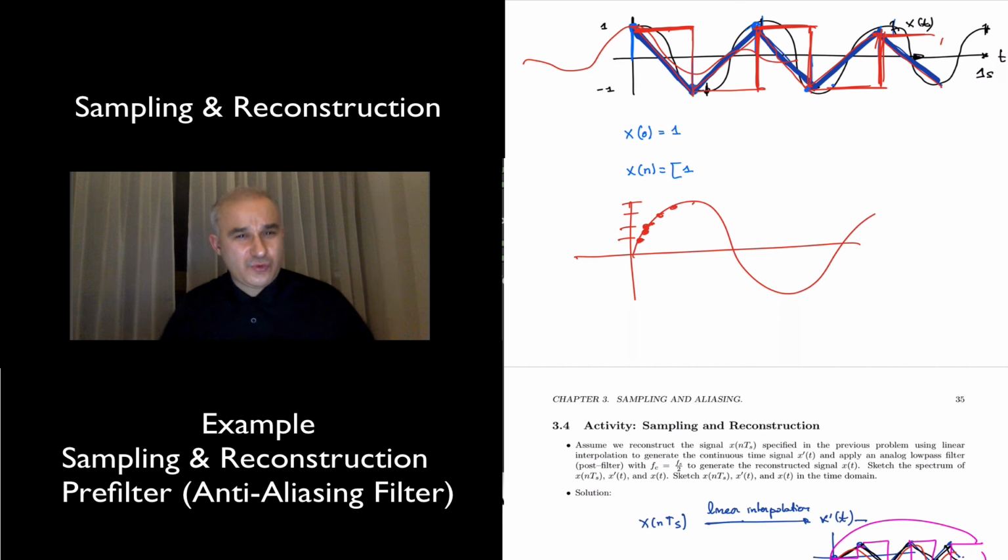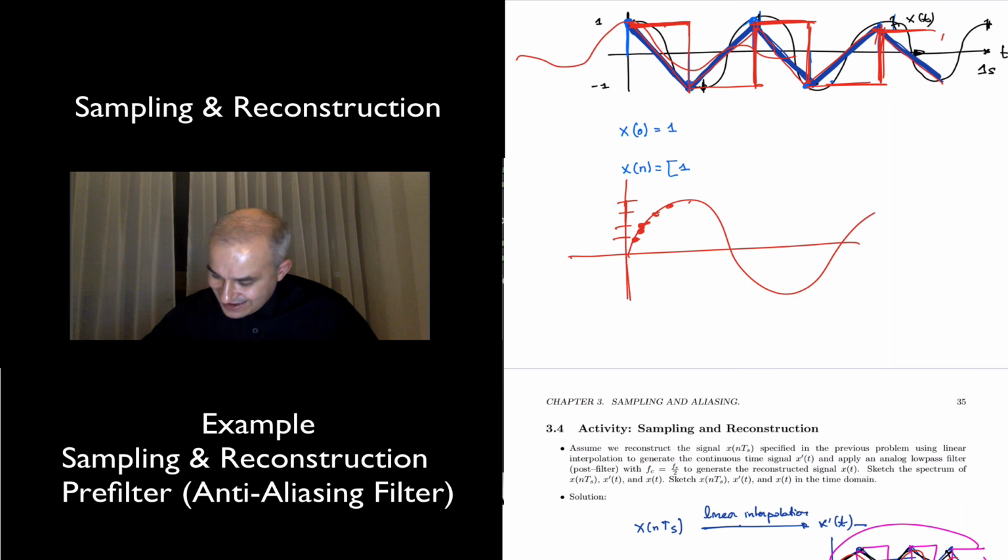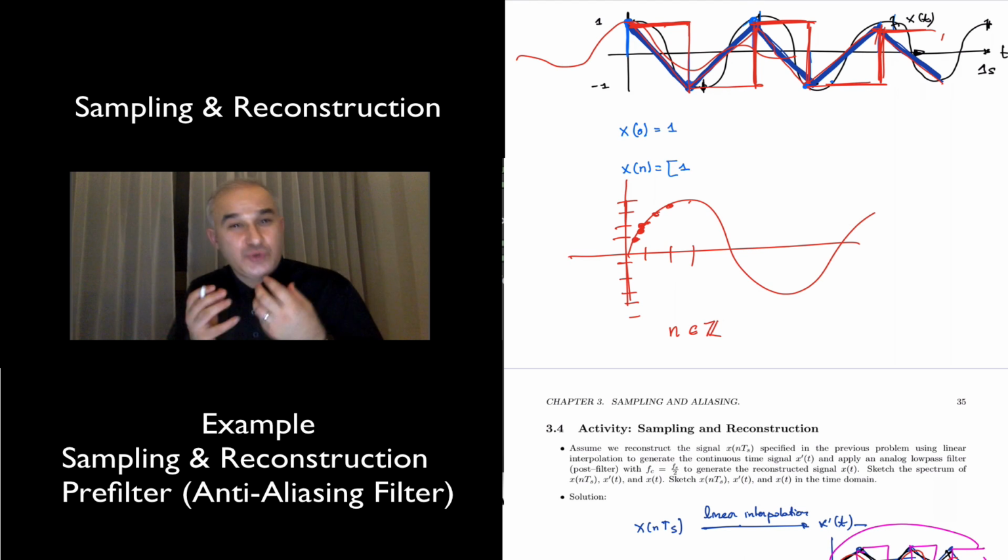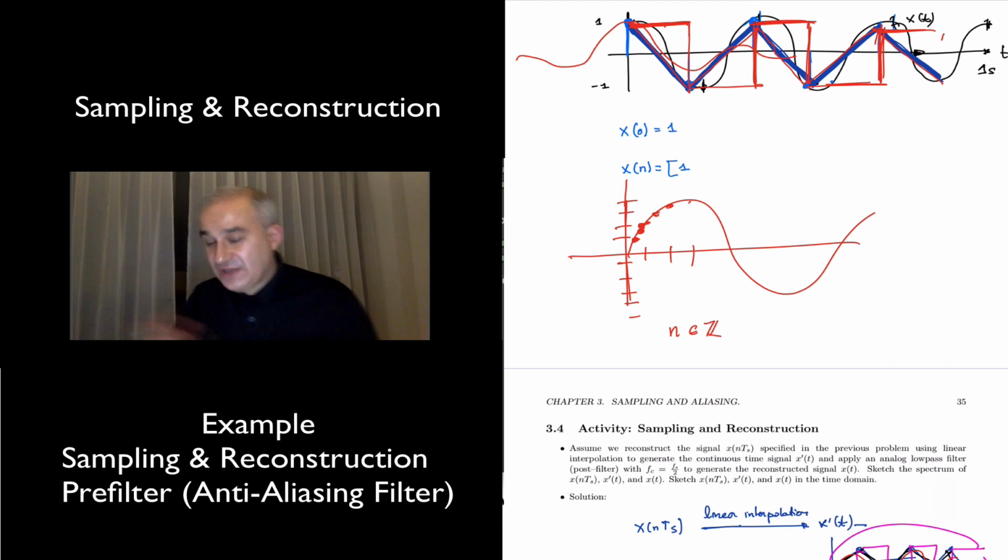And so effectively, once you have a finite set of levels, once this is quantized to n number of bits, not only have you made the time discrete, an integer, but the amplitude, although you can have as much precision as you want, is now a countable set, so it's also an integer. That's why it's going to be great to be used with a processor.